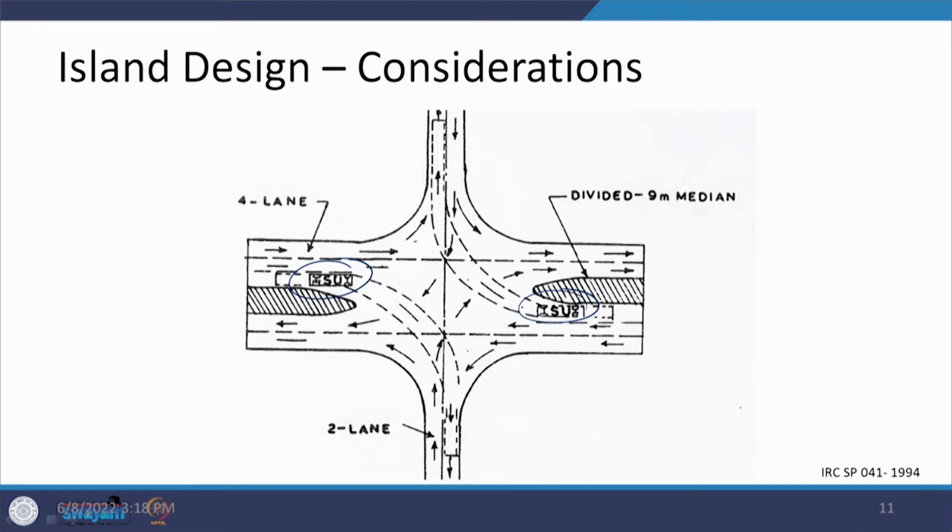So, if this is a single unit truck, then it is going to take a turn. There is a turning radii for that, and this is being traced for both wheel paths. That means the inner and the outer wheel paths have been placed, and when it comes on this, it should be clear of the center line. So, you can see that that is what is being ensured.